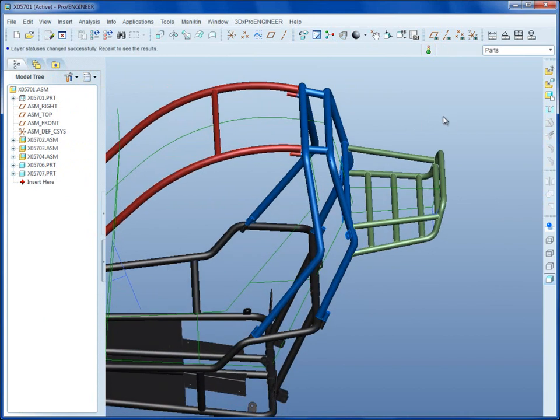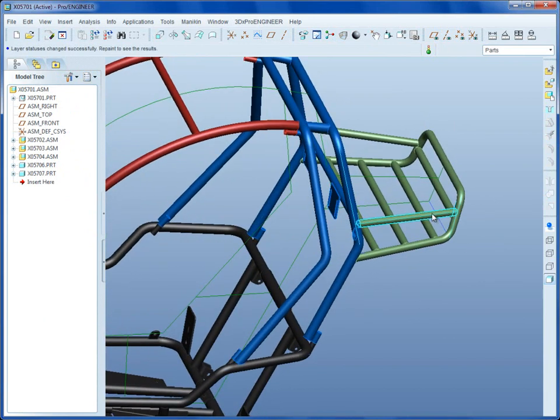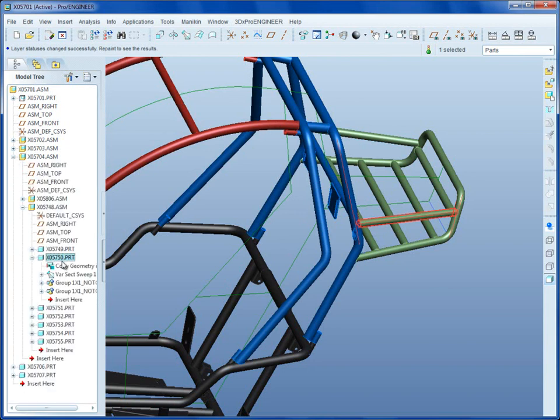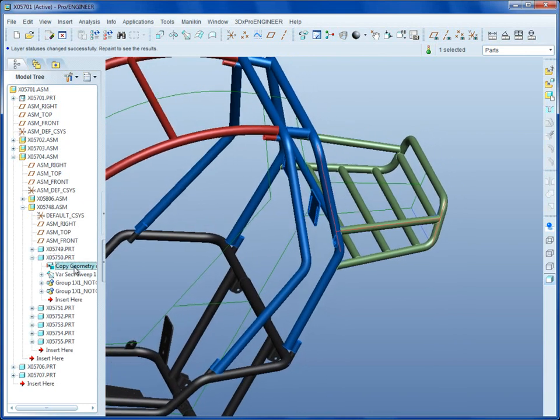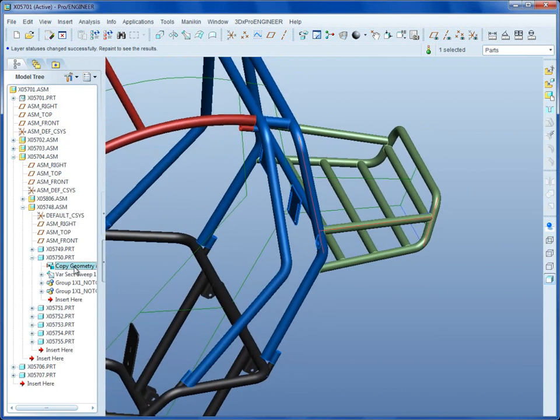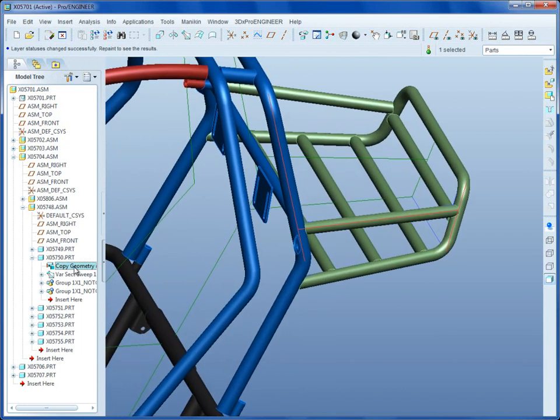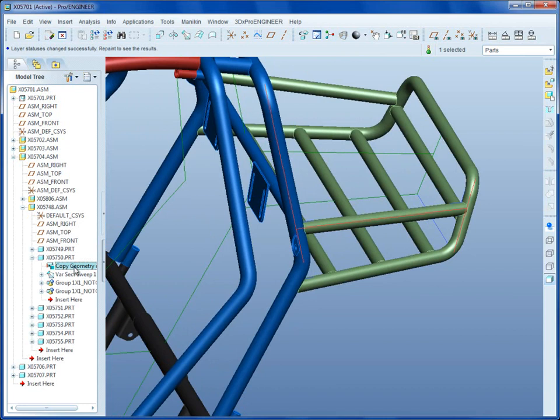Let's look at just one of these parts in particular. I'm going to single out that guy. There he is. You'll see the part starts with a copy geom, and that grabs a couple of curves from the appropriate skeleton. You notice that the curve that defines its overall length and position, as well as the adjacent curves, are the ones that are copied in here.